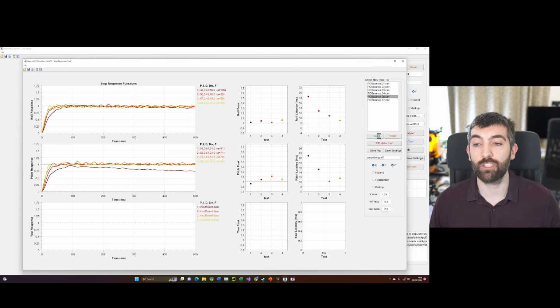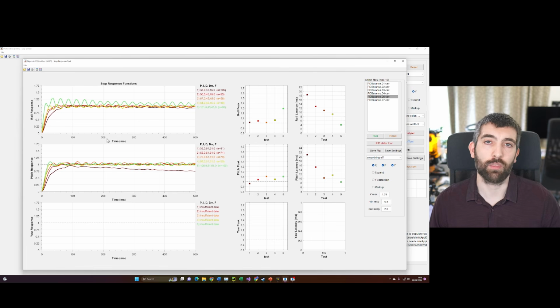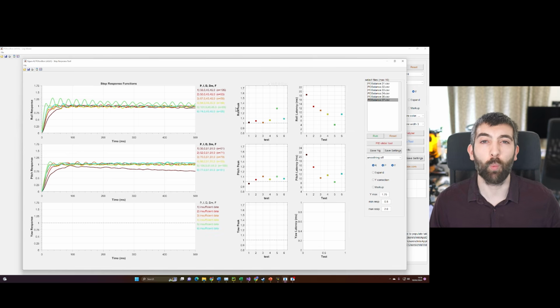If I now go way too far, you can see that with way too much PD balance, so way too much P term, we've got a lot of oscillation, particularly on roll, and also some oscillation which is dying away on pitch. Looking at all of these different values, we can pick the slider values that we think are best. And I've also included a run at 1.1 PD balance, which is halfway between 1 and 1.25, because I think that's going to be pretty much optimum.